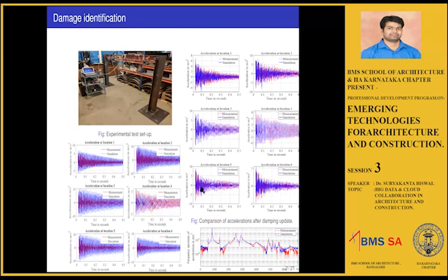Then we did a model for the damping. The nonlinear damping is very critical if you're using time-based damage identification. So we did a nonlinear damping model, and based on the damping model, you can see the model accurately predicts the responses from the structure. So it can identify the damage, and also, once you have the calibrated model, you can predict any response that you want for given types of loading.